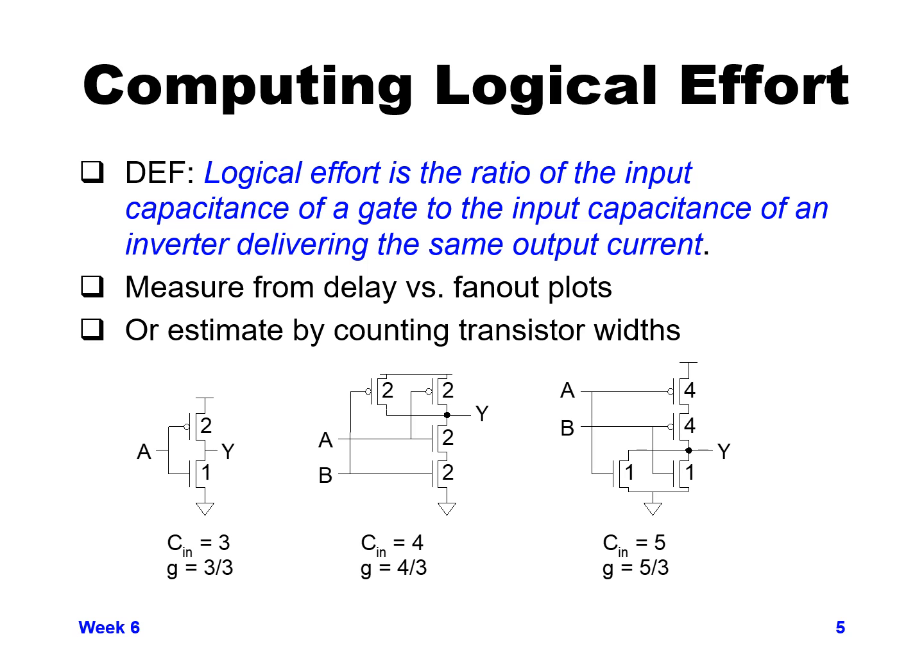So if we look at an inverter, the circuit in the lower left of the figure below, you can see your typical inverter, minimum sized inverter, is a size 2 PMOS and a size 1 NMOS. You add the 2 plus the 1 gives us 3, and that's our input capacitance. Divide that by an inverter delivering the same amount of output current. By definition, since this is an inverter, the 3 gets divided by 3, and by definition an inverter has a logical effort of 1.